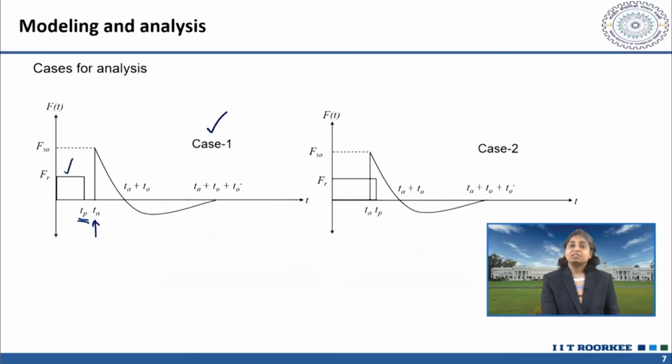So, in between this Tp to Ta time, the foundation is going to vibrate freely, but the case can be that the pulse loading is continuous till the positive phase duration of the exponential pulse loading.